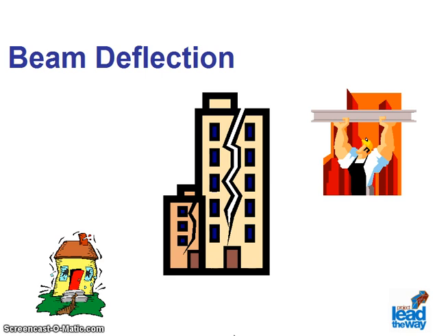Deflection of a simple beam is more important than bending. Deflection can cause a ceiling finish such as plaster to crack or a floor finish such as tile to break. Both are undesirable. There are other concerns. Excessive deflection may cause building vibrations that can lead to load failure when the beam resonates, or excessive deflection may shorten a beam to cause it to slide off its support.